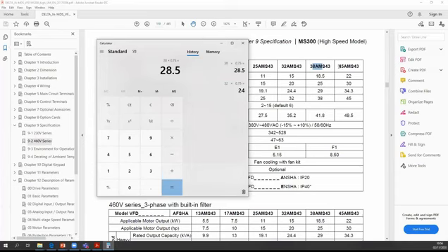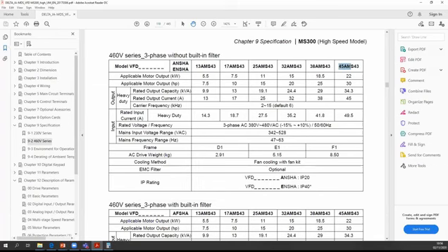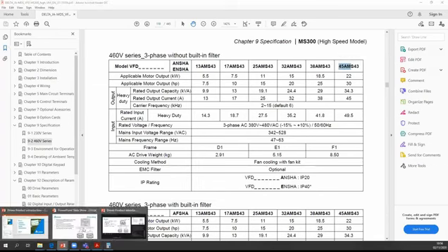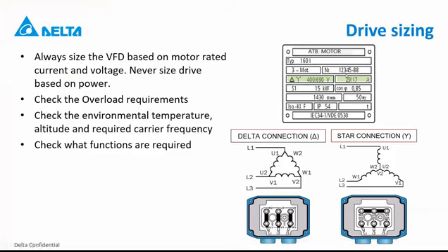So you would have to use actually a 45 amp drive in this case. But also for a spindle motor which is rated at 1000 hertz, you can expect that the rated current will be slightly different. In any case, this is the principle by which you size a drive based on carrier frequency. So I hope this answers the question.